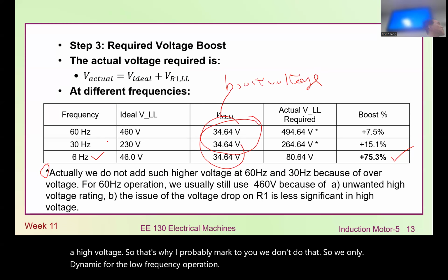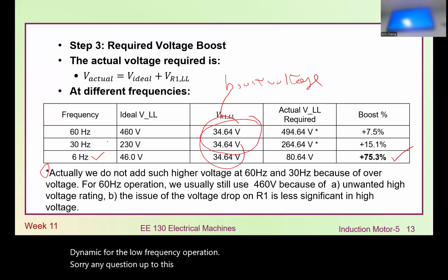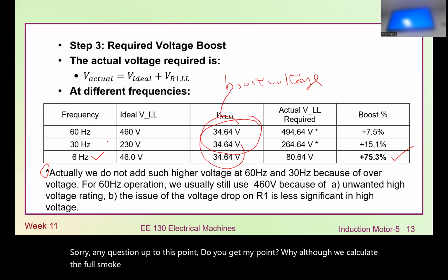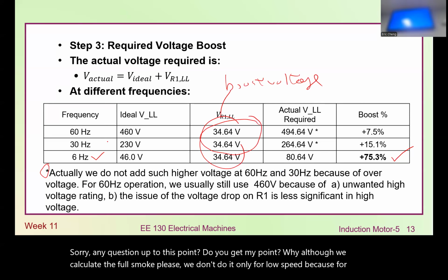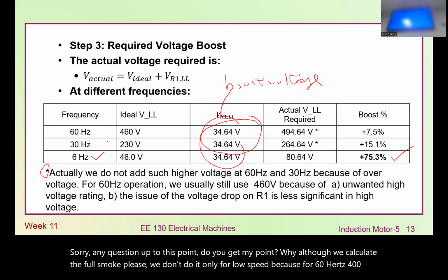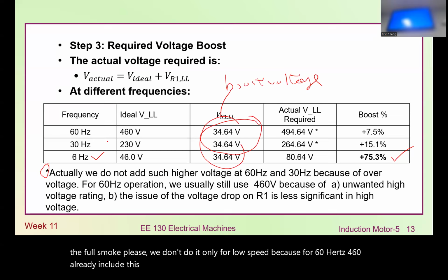All right, any question up to this point? Do you get my point? Although we calculate the boost voltage, we only do that for low speed, because for 60 hertz, 460 volts will already include this kind of phenomenon.